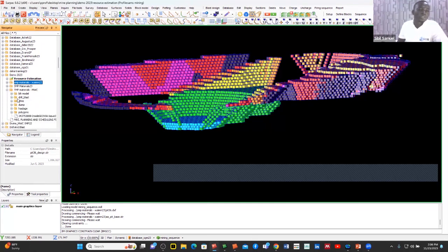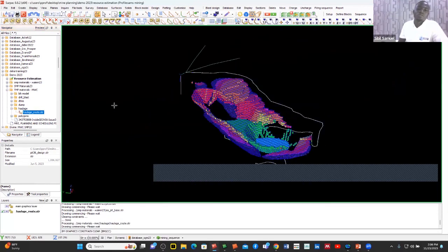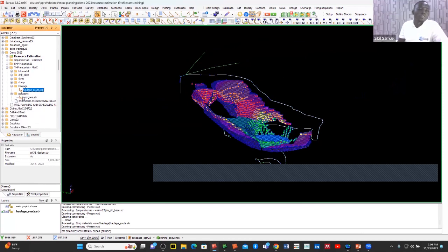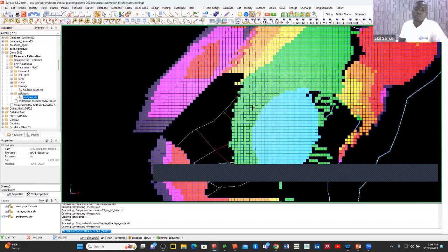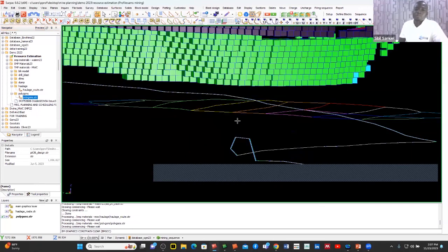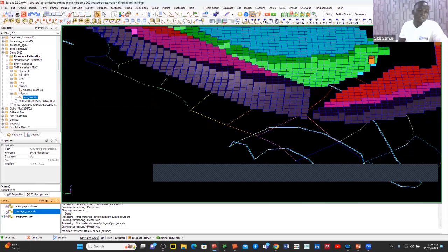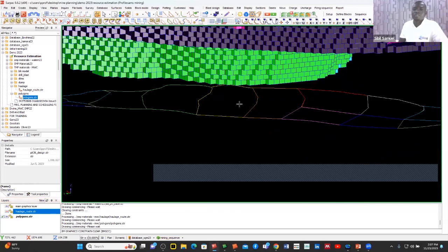You should have the block model, you should have the GTM, that's the topo, the pit, or the DOM, all those things. You should have the haulage. You can digitize it in the pit and all those things. Have your haulage route and all those. Then the polygons. That's for short-term scheduling; we have long-term scheduling in Minesched where you do a lot of things. But if you want to do short-term, just a bench kind of mining, you just get your polygon, for example. And then once you digitize the polygon, use the polygon, and then you get into Minesched. And you can just go to that.